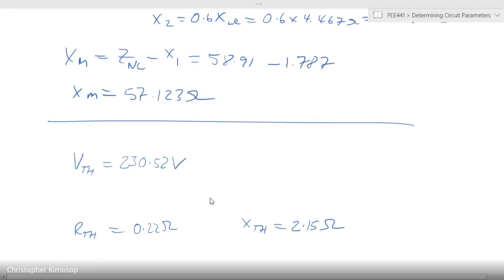Please work through to the maximum torque, find the maximum torque, and also find the starting torque based on this. So you can do a bit of practice in the text. Make sure you have familiarity, or you're conversant, with the power flows, the torque slip characteristic, and also this determining of the circuit parameters from the three motor tests that we do.